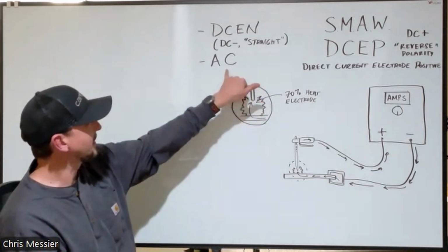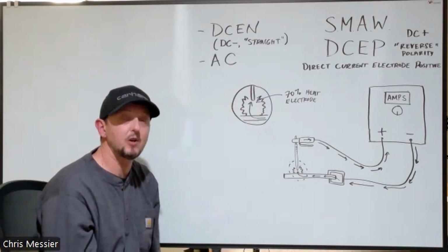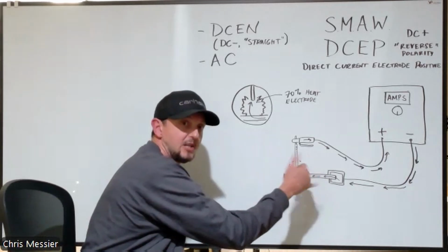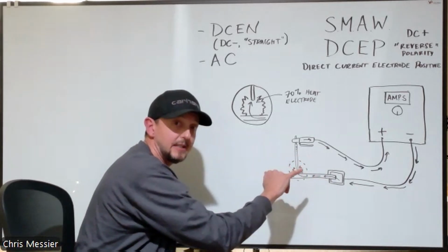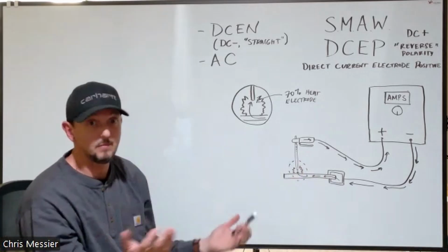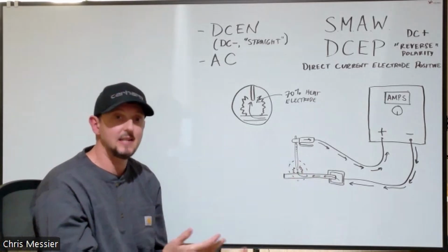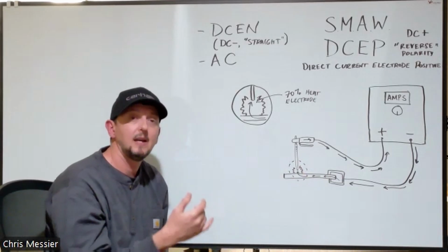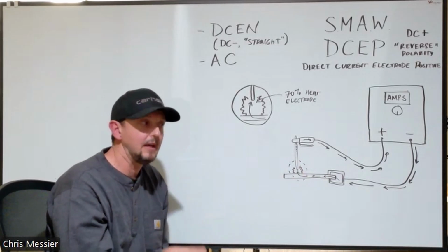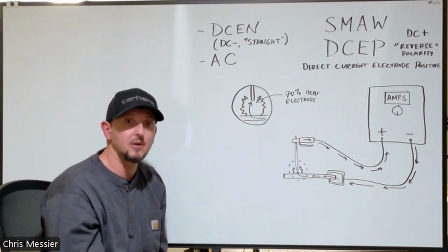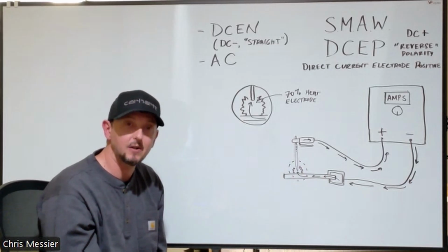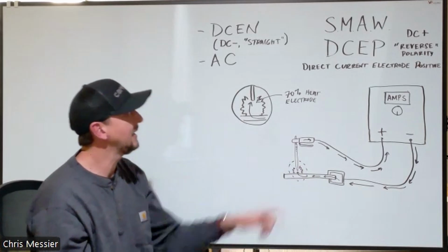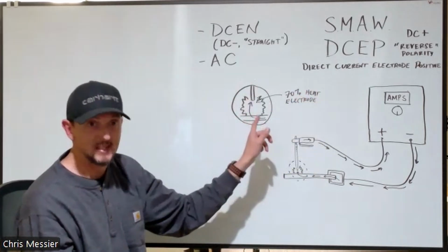And that brings us to our final polarity, which is a type of current, alternating current, which means that it would actually change direction, change polarity, a lot of times per second. The standard would be 60 hertz. That means times per second. It would be switching back and forth. Our inverter machines are usually about 120 hertz, times per second that it's switching between DCEP and DCEN.